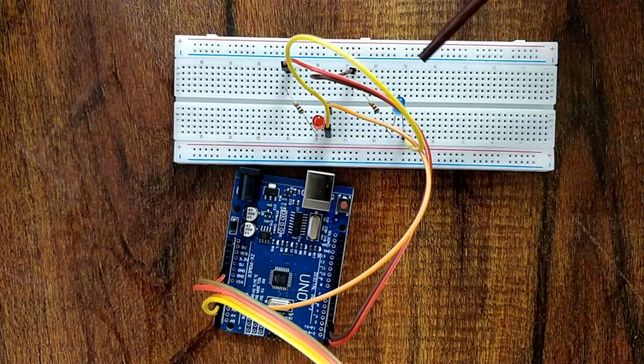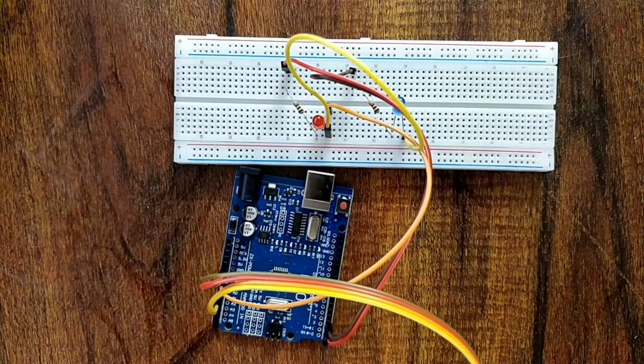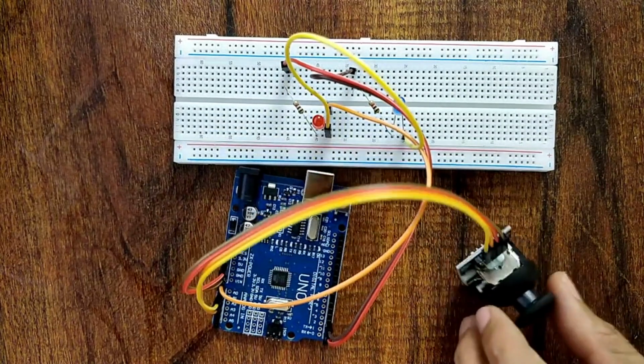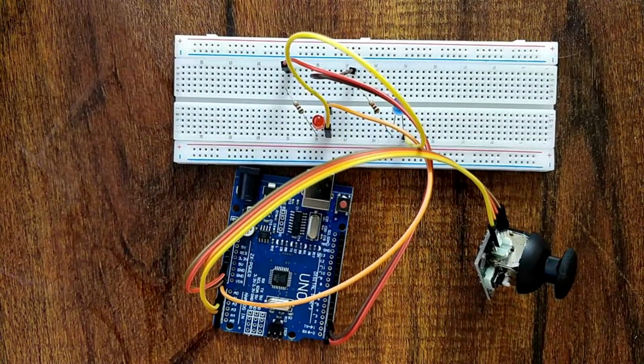These resistors are 1 kilo ohm each, thereby restricting the current flow through the LEDs because they are very sensitive in nature. They can only support a max current of up to 20 milliamps. Anything above that can damage them permanently. Now our hardware setup is ready. The only thing remaining is generating an executable code out of our Simulink model and then flashing it on our Arduino board. Then we can give our input through the joystick module and observe the output. So let's get to it.